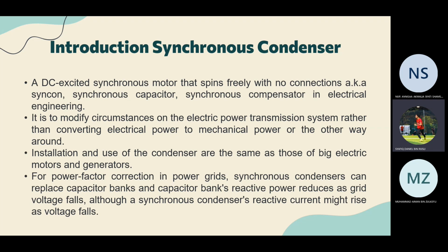Installation and use of the condenser are the same as those of big electric motors and generators. For power factor correction in the power grid, a synchronous condenser can replace capacitor banks, and capacitor banks' reactive power is reduced as grid voltage falls, although a synchronous condenser's reactive current might rise as voltage falls.